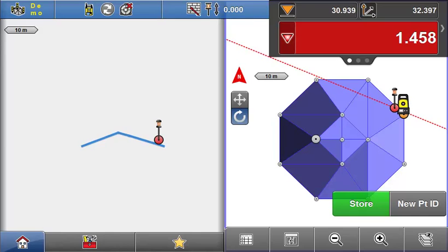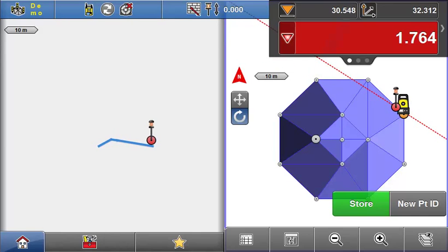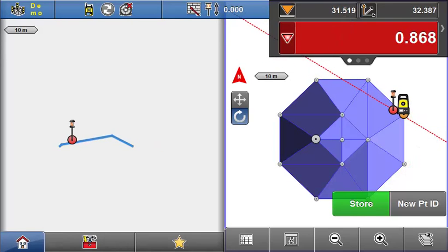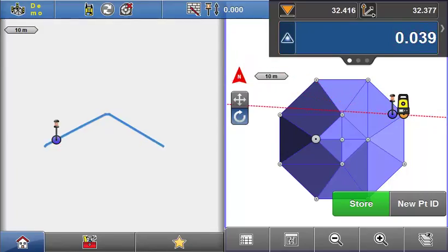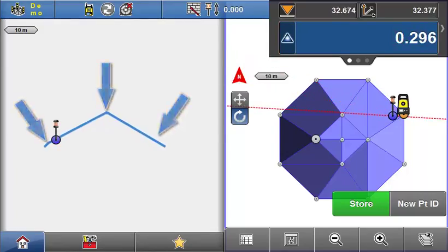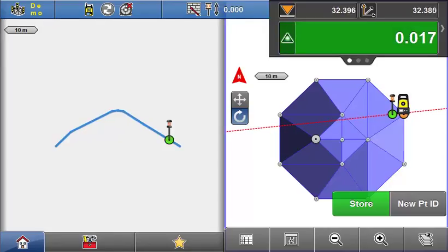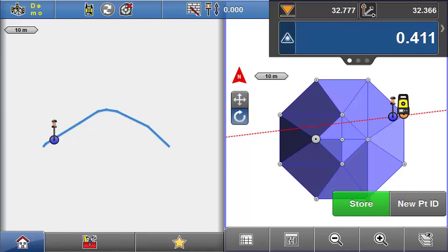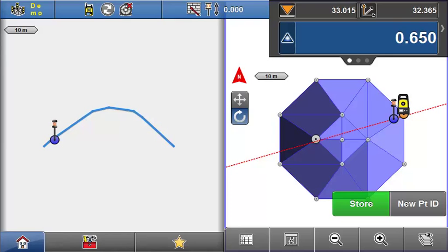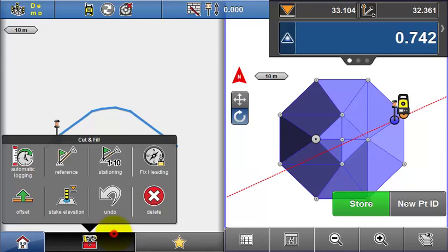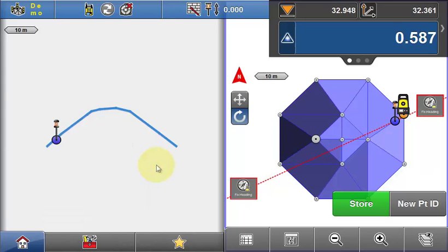In the map view, the cross-section is represented by a red dashed line, whereas in the cross-section view, the surface is represented by a thick blue line, with the actual position shown. Depending on the solution, the represented cross-section could be created perpendicular to the walking path or by a fixed heading of the cross-section. This setting is available as a toggle button from the toolbox.